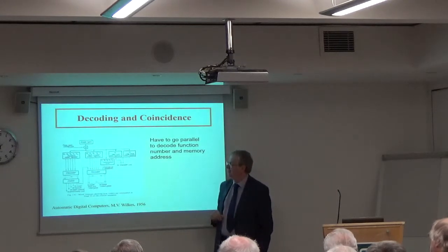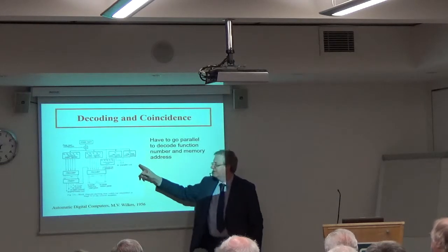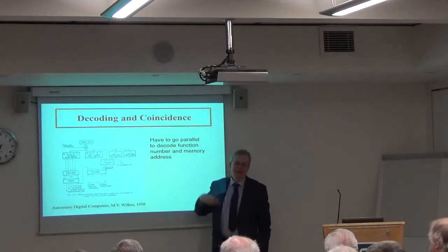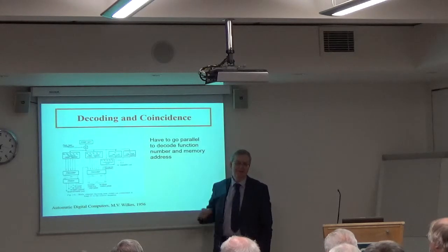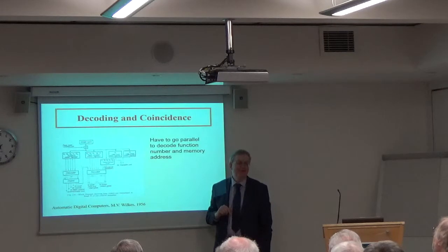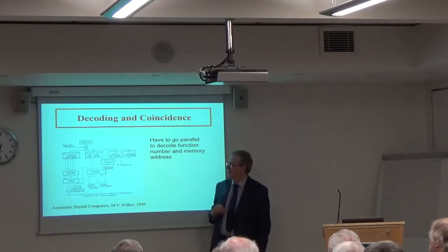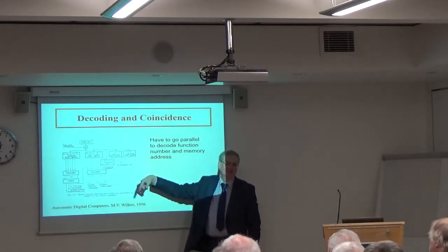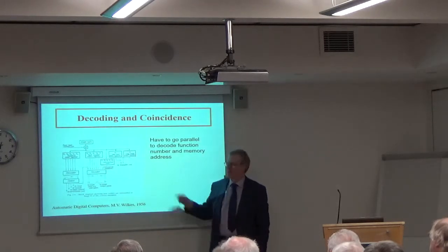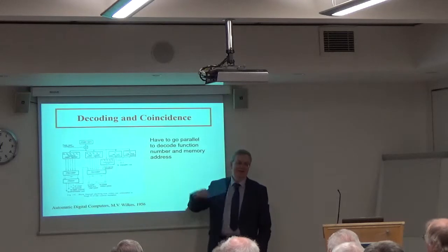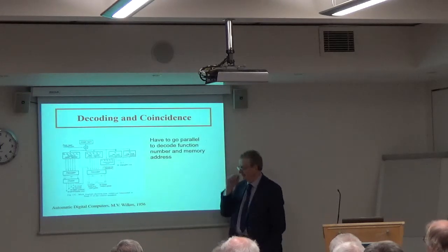And similarly for memory, the way the memory works is there's a part of the machine called the coincidence unit that has a counter that's essentially free running, and that's telling you which word in memory is the one currently coming out of or going into, depending on the point of view, the delay line store. And so to address store, you assert the address, the coincidence unit flips the signal up when the address you assert matches the counter, and then you know it's time to open the gates and move data in and out.